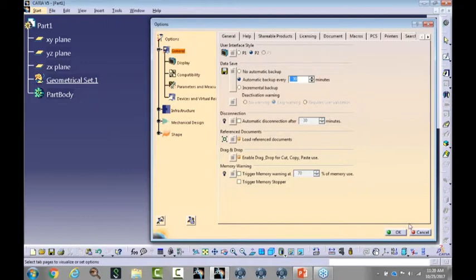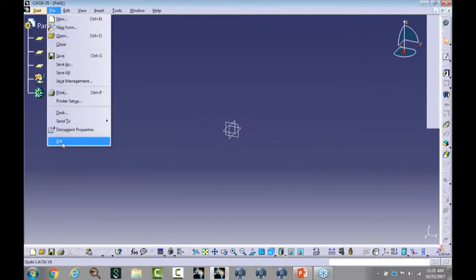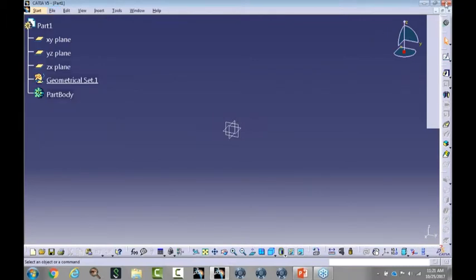Now, let's talk a second about shutting down CATIA and being nice to your comrades on the floor. Basically, the shutdown of the product to reinitialize it, under the Start menu, there is an exit. Under the File menu, there is an exit, and you have the X click in the upper right-hand corner. Forget the X click in the upper right-hand corner. And let me tell you why. There's a secret that's going on behind the scenes here. When you grab a license, when you're initialized in CATIA, that license is held, and a timer goes off right away. That license is held for 17 minutes.